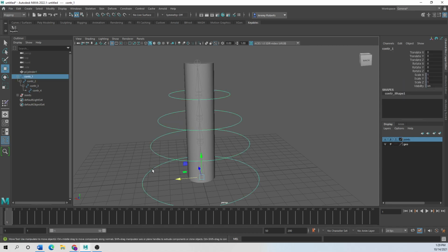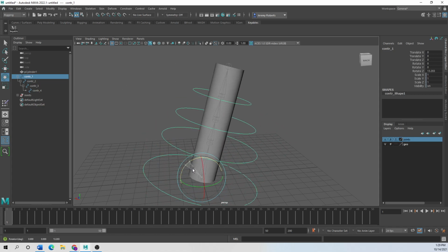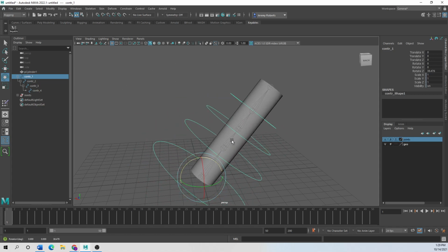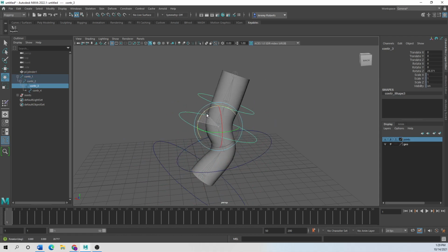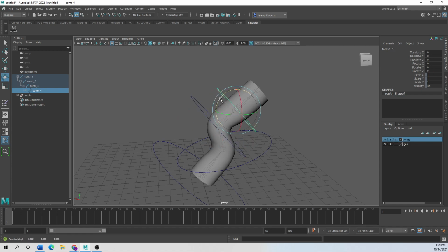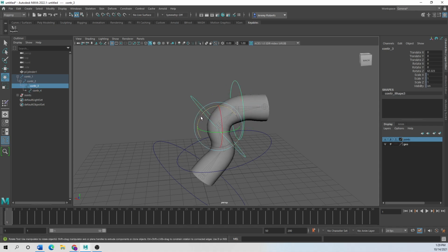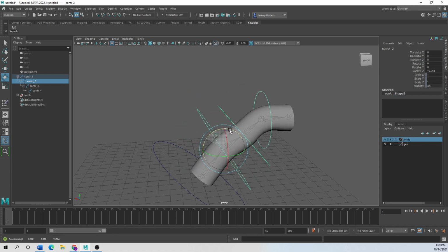So this works with forward kinematics, and you'll see my skeletal system running up the piece of geometry there. It controls every single joint that I've listed. This is a demonstration of forward kinematics where I can keyframe every single one of these controllers independently, because I have constrained a controller to each one of these joint roots.